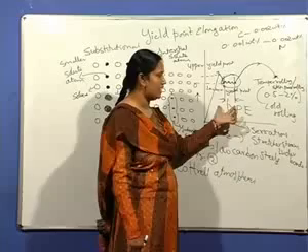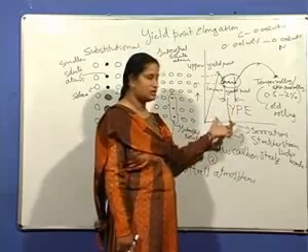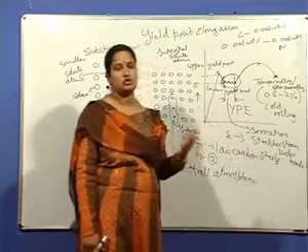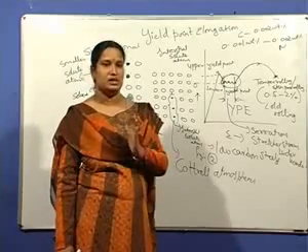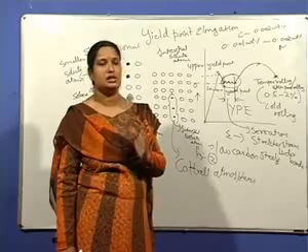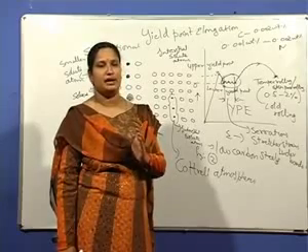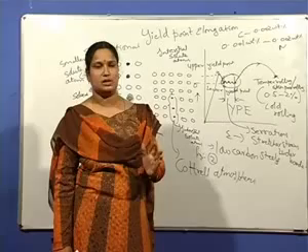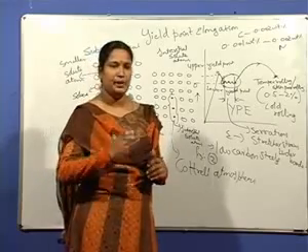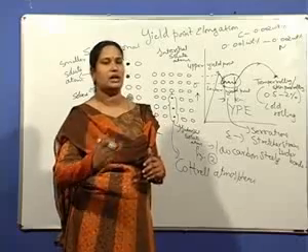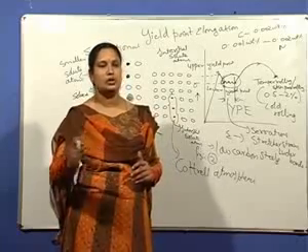That is also known as serrations in the stress strain curve. It is also known as stretcher strains and Luder bands. The main reason for this is the interstitial solute atoms like carbon and nitrogen, which lock the dislocations. The dislocations are continuously pinned and unpinned, or locked and unlocked, by the solute atoms.